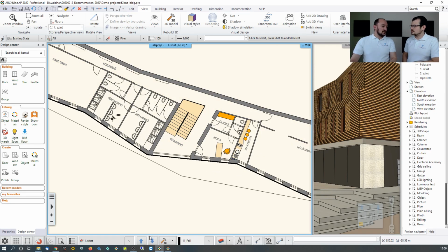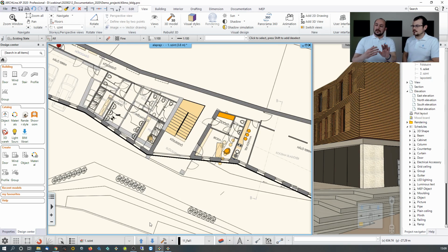And there is an important thing: if you control click on any of these buttons, you can do the same thing with the inactive floors. So up and down changes the active floor, and control up and down, I mean these buttons, will change the inactive floor. So you can use the same kind of page swapping ability between inactive floors as you could do with the active floors. Returning back to this topic about the framed wall structures, how do you represent them?